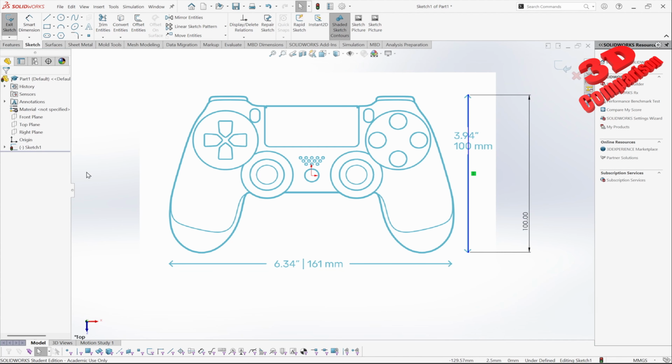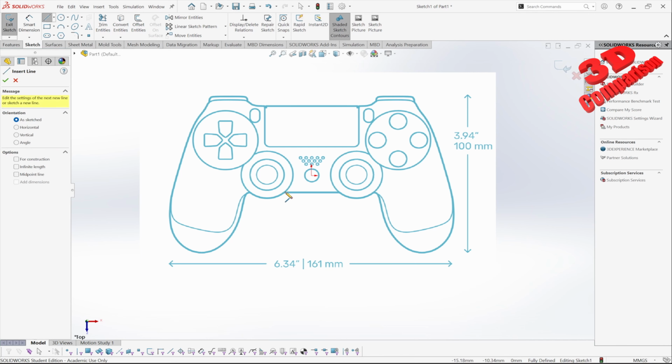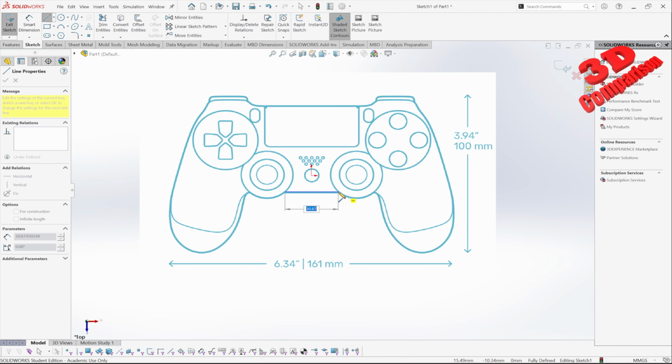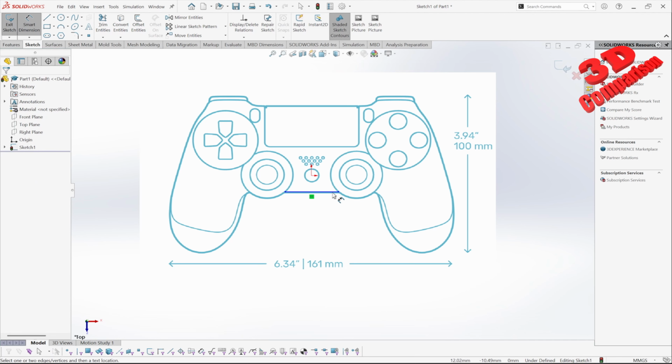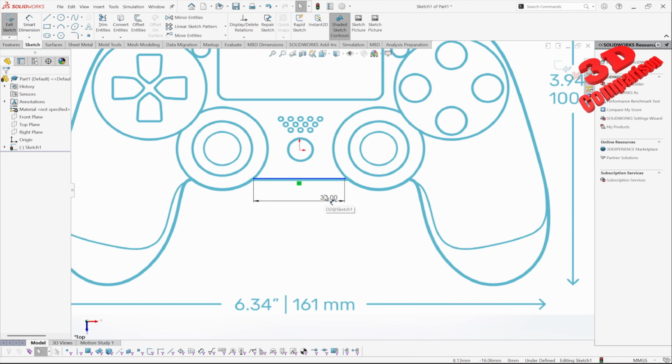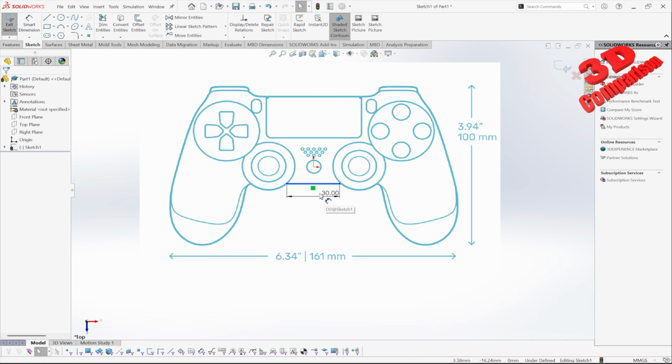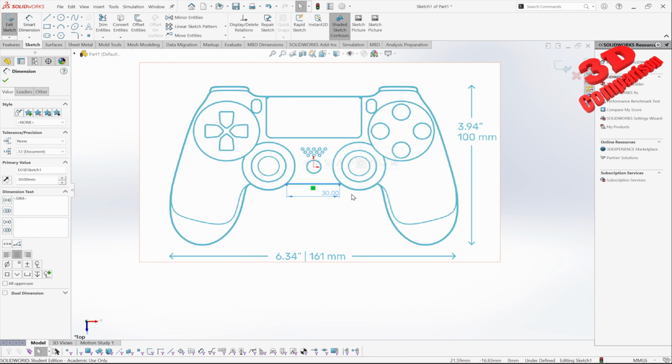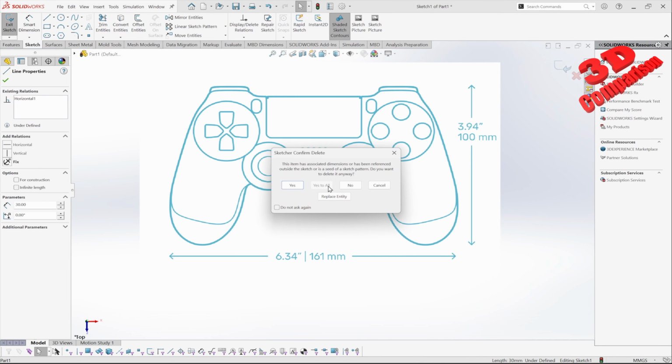If I will delete this annotation, that sketch and the line, let's say that I want to trace something, maybe I want to trace this, that will have around 30 millimeters, and that should remain as 30 millimeters. So as you can see in my case, this will not scale the image. I usually prefer not to add sketches directly within the same sketch where I added that reference image, and that is something that I usually do.